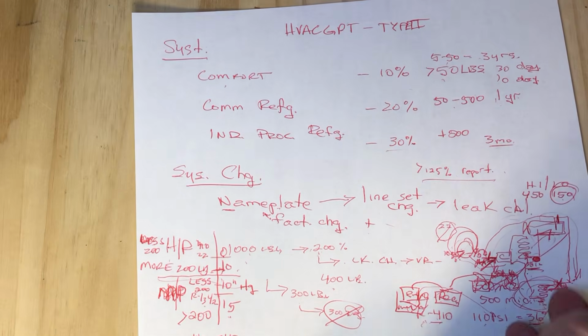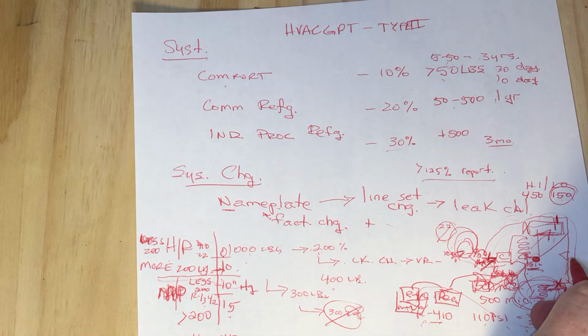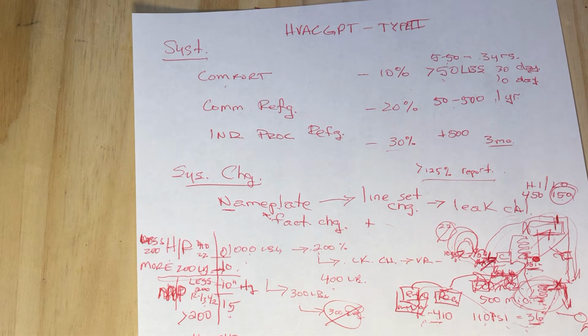So a couple other things about this refrigeration cycle. You might have some accessories like a filter dryer. Anytime you open the unit for repair, the filter dryer has got to be swapped out with a new one. We don't leave the old one in play. And then it also might have a sight glass moisture indicator on there. That sight glass, if it freezes up, can be cleaned off with isopropyl alcohol. A couple of my students mentioned that they got that one wrong, and that's an easy one to get right. Just alcohol will take the frost right off, and that's what you should use, not water, definitely not oil or any other chemicals that could be dangerous to it.